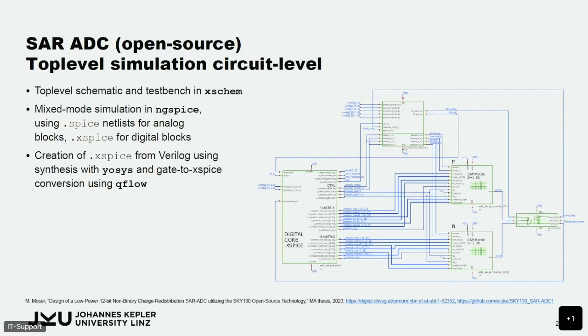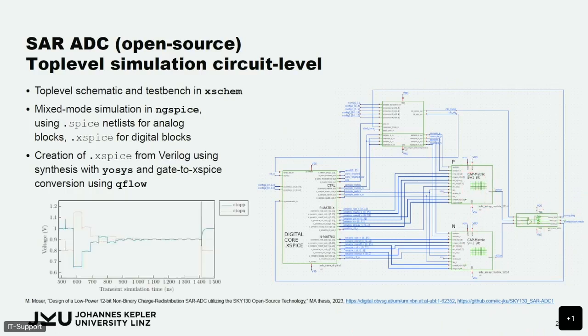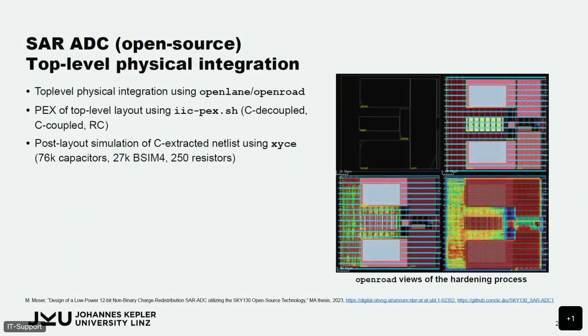If you really want to know what's going on, you need to simulate the analog pieces on an extracted level. So we did then a parasitic extraction of the capacitor matrix and the comparator. By the way, here's the simulation result, so it really works. Yeah.